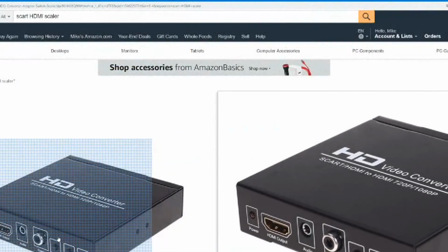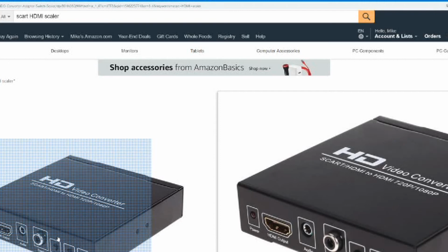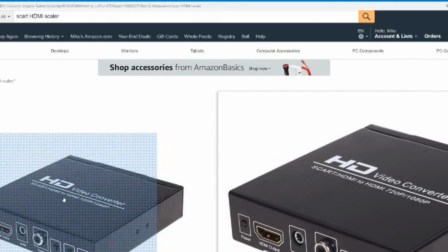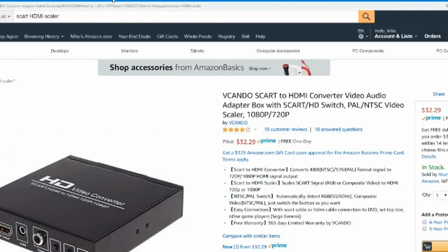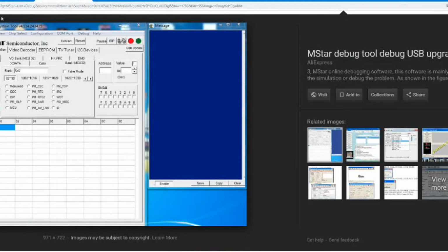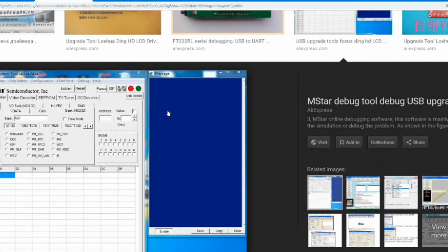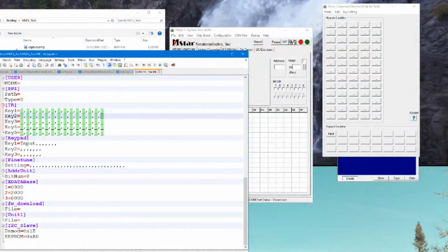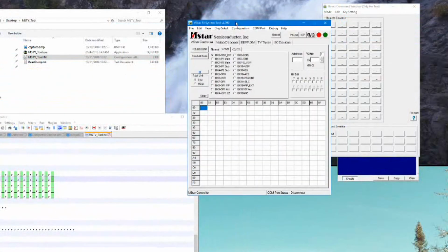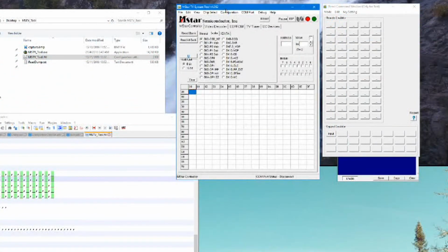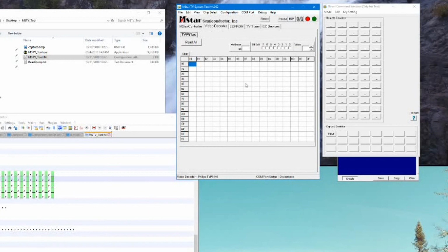Like I said, I've made a few that have a small Arduino inside with a few buttons that I've drilled into the top to do things like set to those non-standard video inputs or change aspect ratio just by sending button press combinations. And so if anyone has a lead on one of these newer Mstar system tools, that would really be great, as it would help the whole community be able to fully embrace the power of these little Mstar scaler chips. Feel free to let me know in the comments if you have any additional info or know where we might be able to acquire newer versions of this, or if you possibly have a manual of this IC and what registers here actually control what, and that would be great.